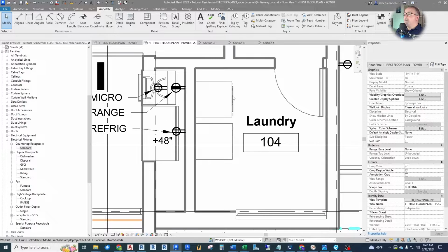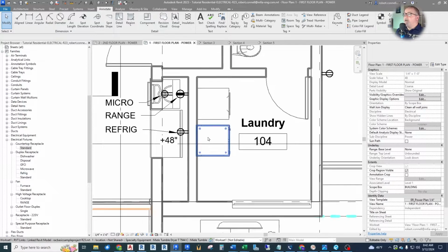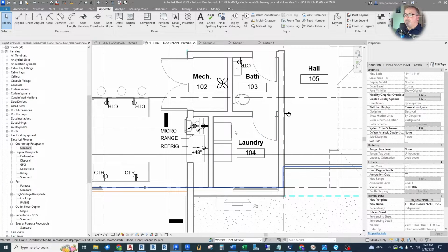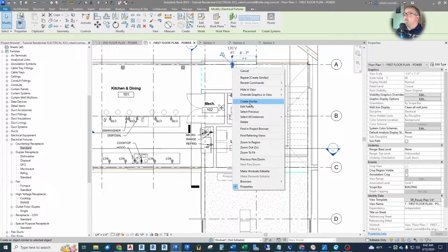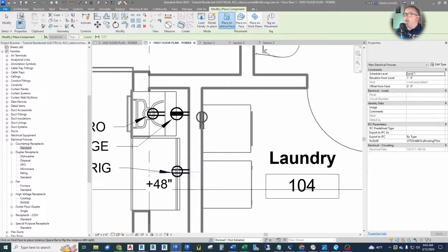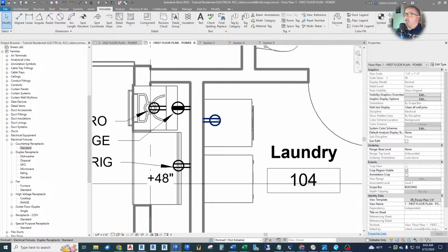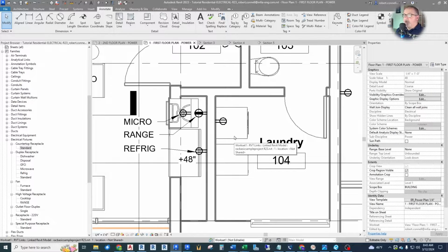Now the laundry. I think we already looked at these, and the architectural model determined that that's the washer, and this is the dryer. Now the washing machine gets a standard 120 volt receptacle. So we can use this guy. Put that back here for the washing machine. Again, we hit something, so we want to find clean wall and then drag it in. That's for the washer, and again, residentially, codes say we use a 1500 watt circuit for the laundry room, washer itself, and other things in the laundry room.